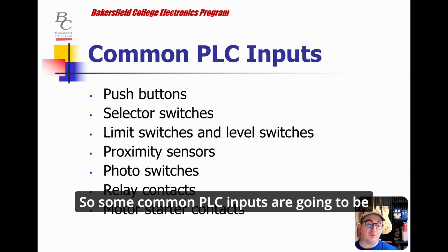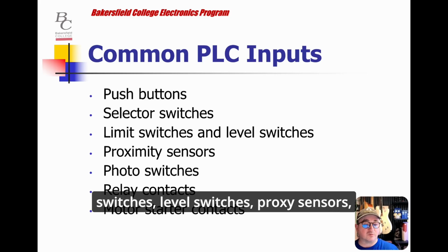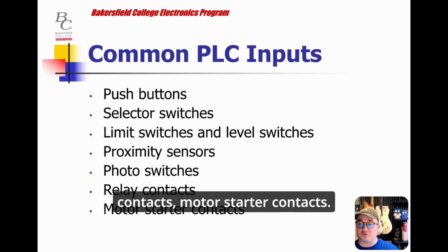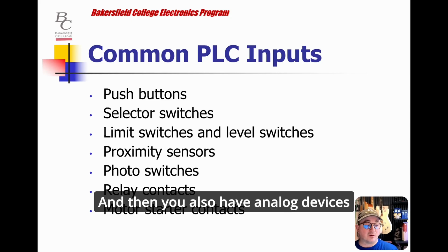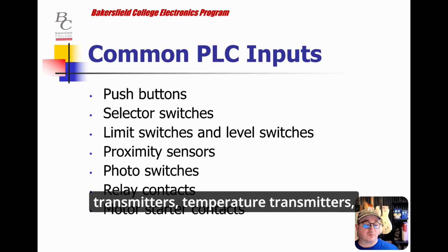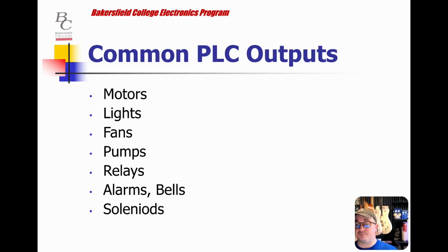So some common PLC inputs are going to be push buttons, selector switches, limit switches, level switches, prox sensors, photo switches, relay contacts, motor starter contacts, and then you also have analog devices like level transmitters, pressure transmitters, temperature transmitters, motion sensors, and various other types of contacts.